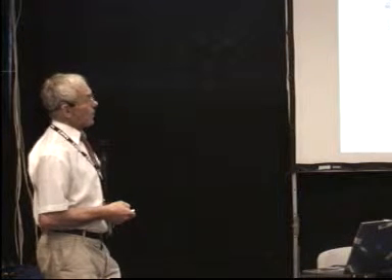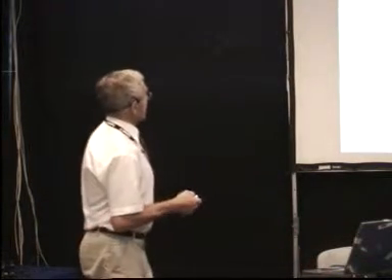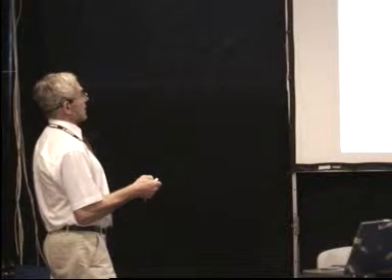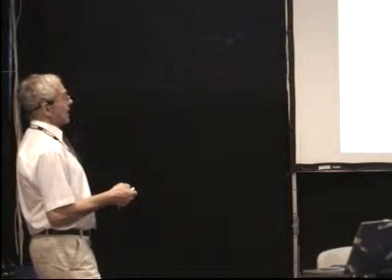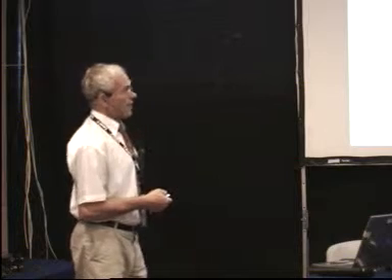And here I come to multi-wavelength conversion, all-optical wavelength conversion. Coming back to the schematic diagram, so far we used only one pump for the parametric amplification. If you use 2 pumps, then these 2 pumps beat together, and if the pumps are 100 gigahertz apart, which is the frequency difference of the ITU grid, so the ITU grid channels are separated by 100 gigahertz, or maybe for more dense WDM systems by 50 gigahertz. In the 1550 wavelength region, 100 gigahertz represents approximately 0.8 nanometer difference in wavelengths.